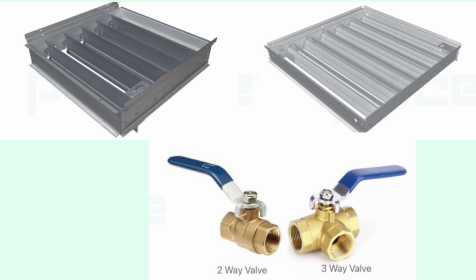Control valves. Two-way valves save pump energy in variable flow systems. Three-way valves maintain constant flow in older or constant volume designs. Select the right flow characteristic. Linear for steady pressure, equal percentage for variable systems, and quick opening for simple on-off. Flow sensors, pitot tubes, ultrasonic meters, or differential pressure sensors all help verify that flow matches design intent.